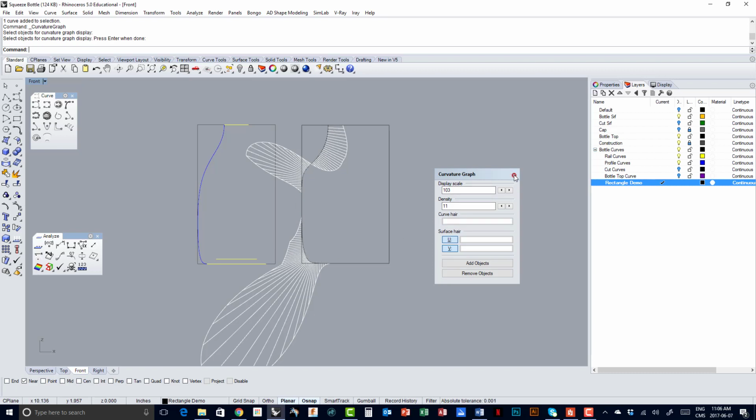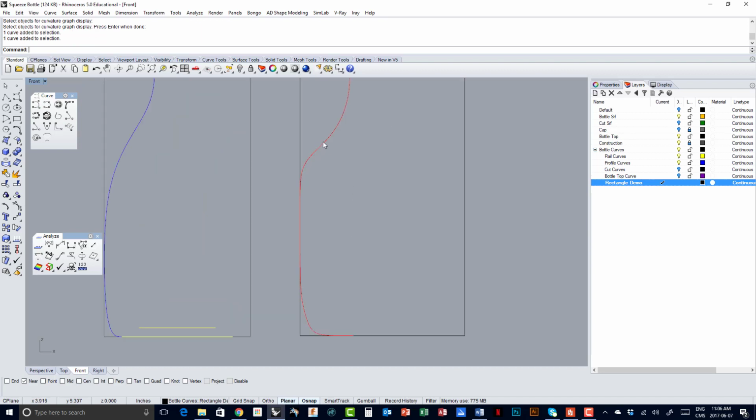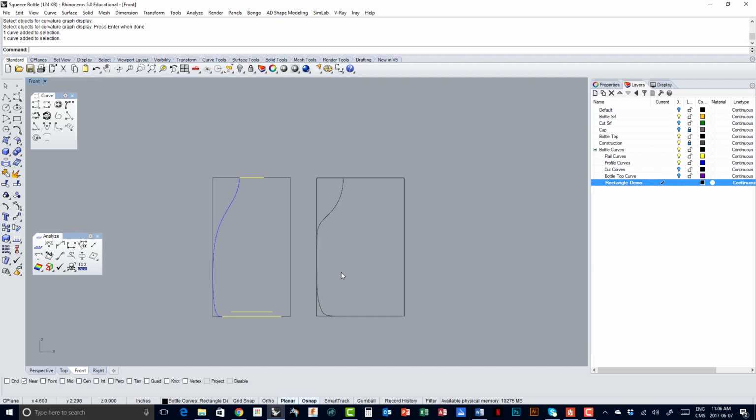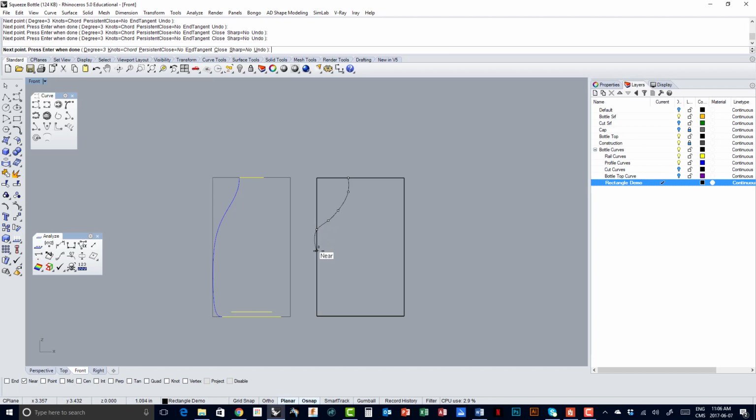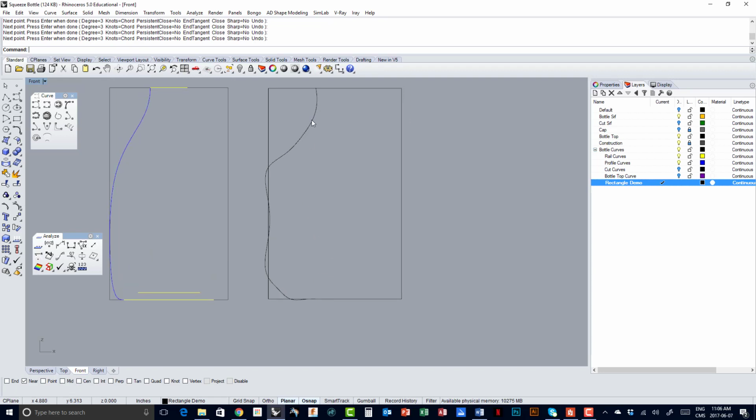So by using the first set, the control point curve, I can snap to that rectangle easily and create the shape that I want just by snapping in near. Now let me erase this curve, and I'm going to show you the difference with interpolate points. I click on that, snap in near like I did here, press shift, place the second point, and start changing direction like this, and immediately I start seeing something weird happening. I keep snapping near and changing direction, and I can see something wrong happening.